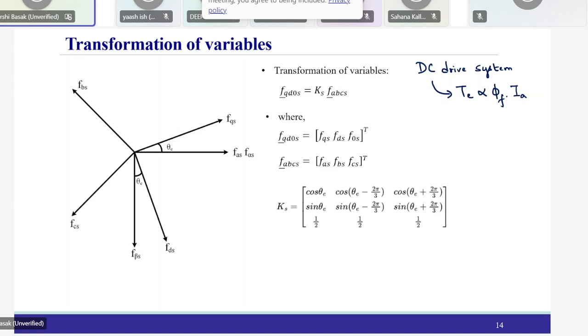So now, the essence of vector control is derived from this: can we do some kind of transformation or some kind of control technique such that we can make the flux, which is producing the torque, and the torque producing component of current orthogonal to each other? Then it will decouple and one will not affect the other. That is what we are trying to do.